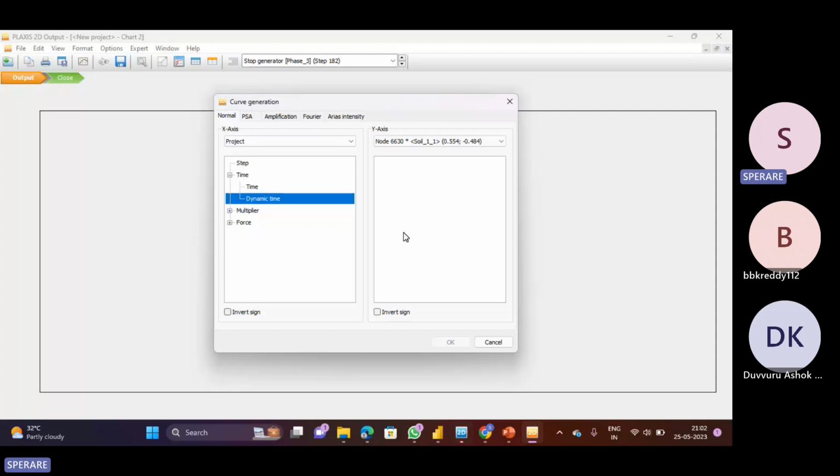So rerun the problem. But sometimes for the dynamic analysis, it takes 8 hours or 10 hours. So for that, don't play like this. Be careful about what points you need to plot. Unfortunately, if you could not fulfill all the points, it is a must that you rerun that. So these kinds of jobs, preferably select in the night time so that you keep it for a run, and in the morning when you come back, you can validate your results as well.